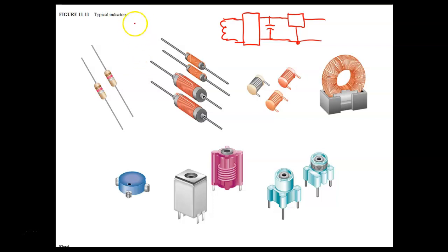Now, there you go. Switching power supply. They usually bring the AC directly in, and then they rectify it, and then they oscillate it. And then they take this output and run it maybe through one diode. They run it through an inductor filter, and then they sense this, and then they bring it back and run a feedback into the oscillator so they control the frequency of the oscillator. These guys you can't fix.